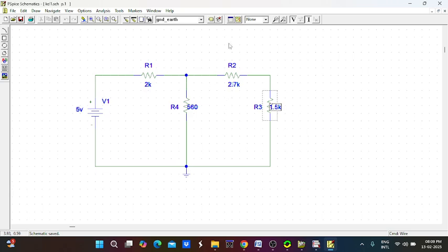And after that, we can use the voltage marker and current marker. So this voltage marker can be placed here before this resistor. How many resistors you have? So in that location, you can place this voltage marker. That means the different voltage drops across this resistor can be shown in this voltage marker.